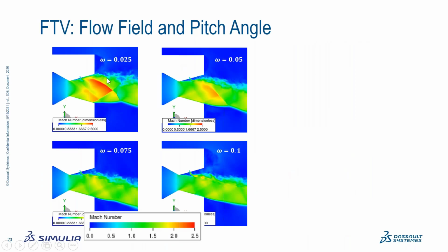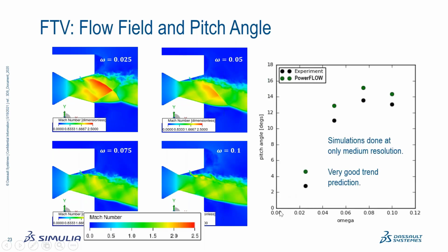When we now look at the different mass flow ratios, again, if you remember, the small value means that the little jet that is ejecting into the nozzle has a very small mass flow, and the larger value has a large mass flow. We can see now how this is impacting the shock structures that are appearing inside the jet.